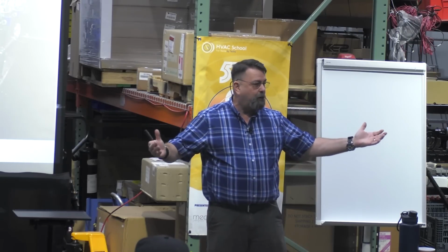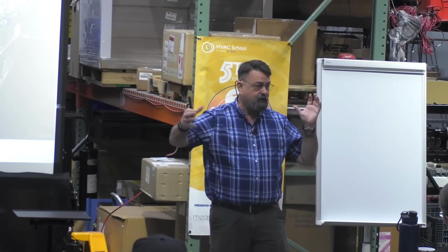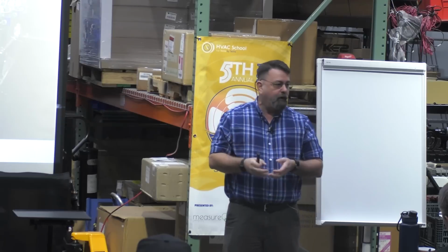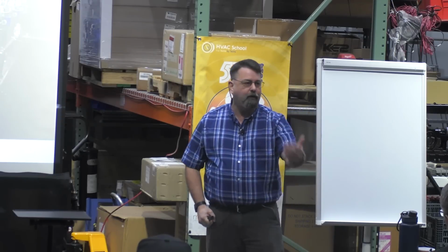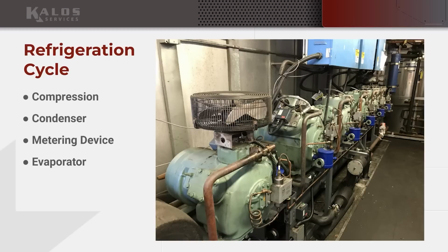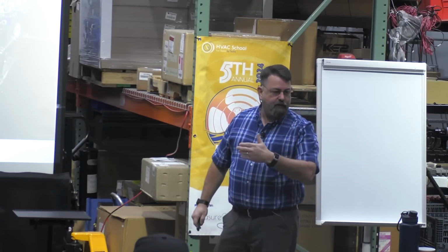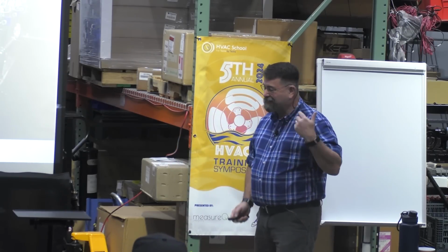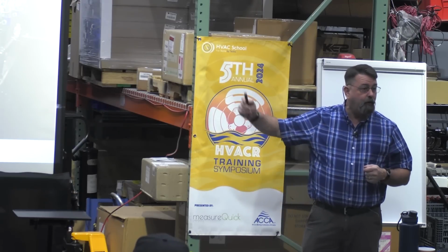That's it, okay? The only time I've got to break that down farther than that big idea of just a variable speed compressor is when I've got to actually work on the one compressor that's tripping out on oil or having some kind of mechanical failure. Then I've got to dig into it and think of it differently. But most of the time, I'm just thinking this is my compressor unit. I need a bigger compressor. Why isn't it staging up, right? I need a smaller compressor. Why isn't it turning off, right? And we'll go through those processes as a technician troubleshooting. But that's the general concept.